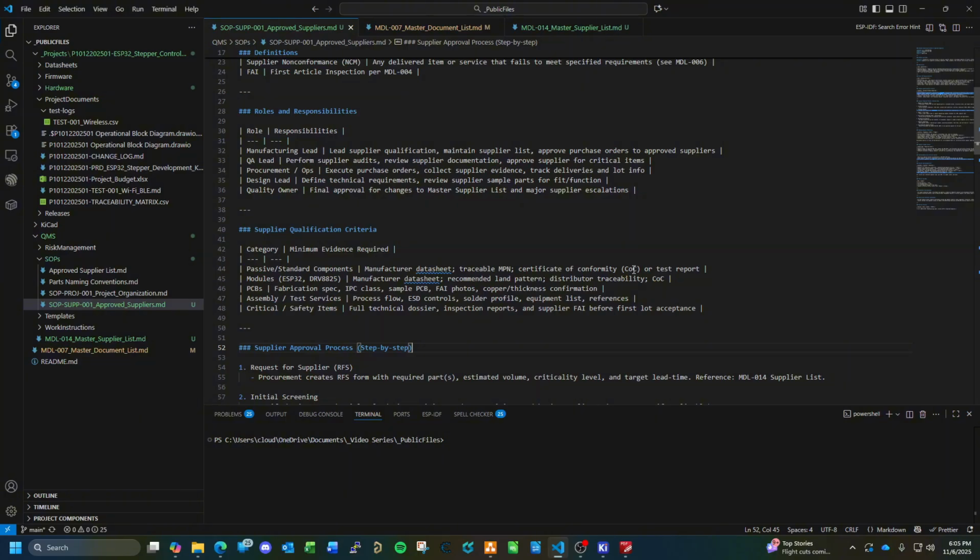So the status of the parts is unknown, the solderability is unknown, whether or not they had the proper process with moisture sensitive devices followed. It's all unknown. Sometimes you have to spend additional money to send samples of the parts out to a test lab to make sure they're actually usable in your process. So that's why you want to make sure you have all this wrangled, all this controlled. Know where your parts are coming from and know what you need to do if something goes wrong.